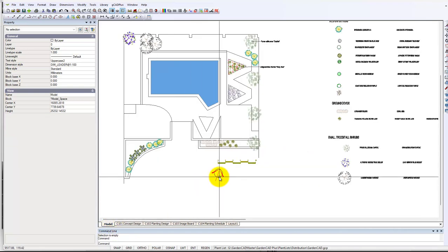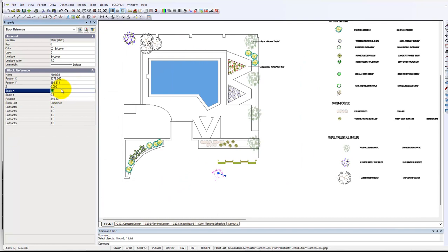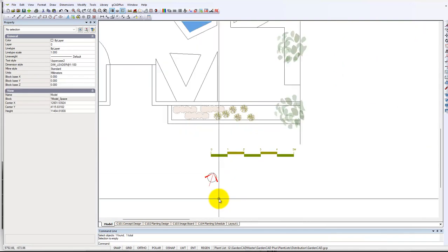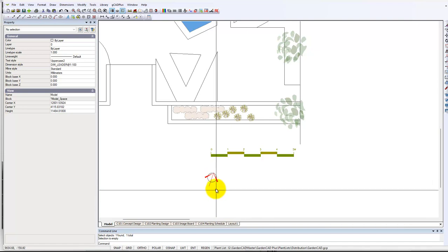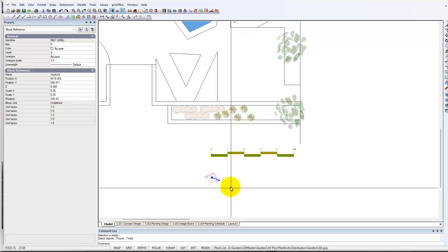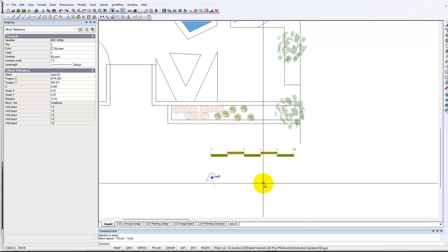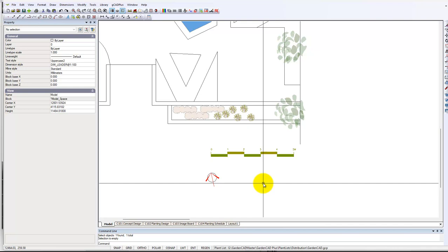You might argue that that north point is a little too large. Let's reduce its size and put its scale to 0.25. We're not changing the distance, we're just changing its size by this technique. But the north point sits in model space and we can grab it. I'd always want to test that this works. We've got a handle so we can look at our site records and spin that north indicator. So it's always going to be there in the full size model of the site.